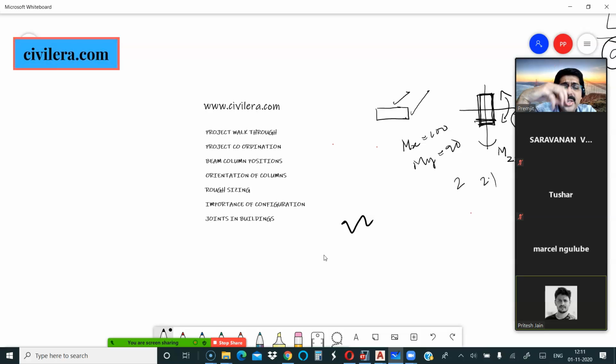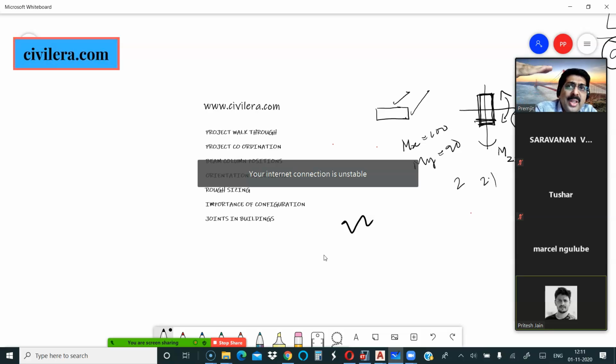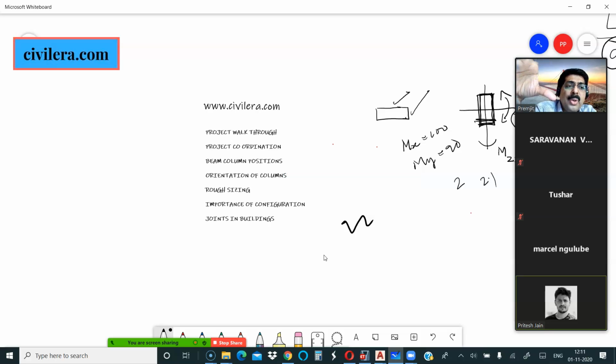Estimate the right effective length, and ensure that you are taking that into consideration in your model. ETABS directly cannot tackle that, because at every story level ETABS breaks your column and takes your unsupported length as 3 meters. So you have to overwrite the parameters. If you know ETABS, by default it will take the story height as your unsupported length and then calculate the effective length. You will have to overwrite that and ensure that the full height is picked by ETABS.